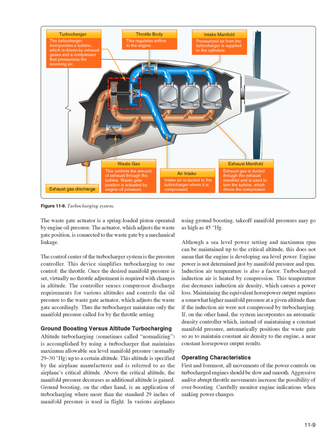If, on the other hand, the system incorporates an automatic density controller which, instead of maintaining a constant manifold pressure, automatically positions the wastegate so as to maintain constant air density to the engine, a near constant horsepower output results.